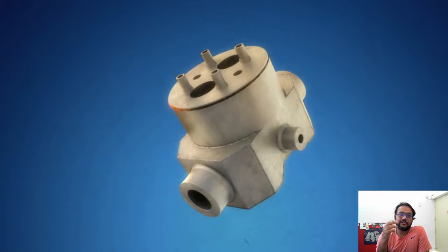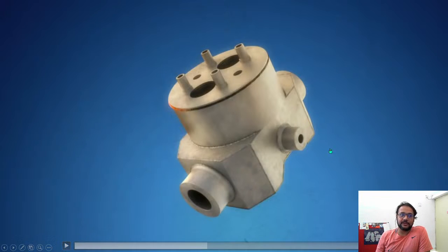So helium is used, and helium will find any cracks or micro cracks. Sometimes, due to impurities in manufacturing of some sheet metal part, very fine holes are there on the surface which cannot be found through other means. So the helium penetration test is done to find out these kinds of leakages.